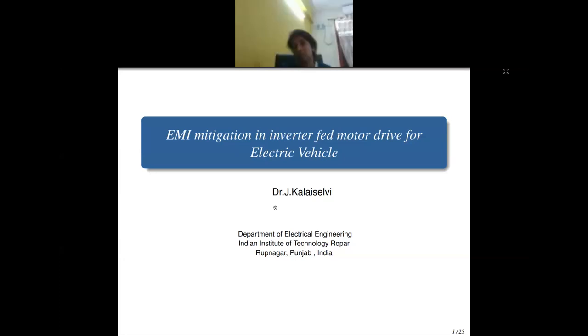Ma'am, there is another question from a PhD student from Arizona State University. I am doing my PhD there, and my research is on powertrains for EVs. I have a 10 kilowatt hardware setup where I am using an RL load to model the 10 kilowatt motor. In an actual motor, the frame will be grounded and a parasitic capacitor will be there between the motor frame and the primary windings, so leakage current will flow through that capacitance. My question is, some papers show leakage capacitance and a small resistance in the leakage path. Do we have to use